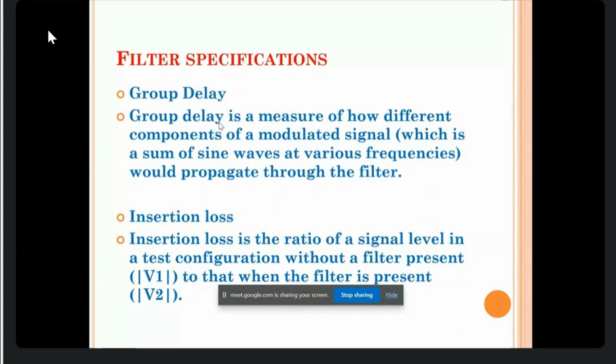in that, most of the filtering or receiving we do in the same IF band. That is, your microwave band, maybe in the 12 gigahertz, that comes back into the IF. Similarly, we are using some techniques in mobile and in all our microwave applications. If you insert a filter in between, that also gives a loss, that is insertion loss. Basically, we know that we mathematically derive it based on the S parameter, the scattering parameter.